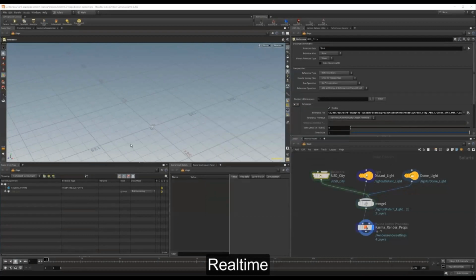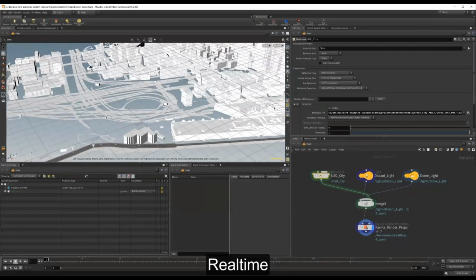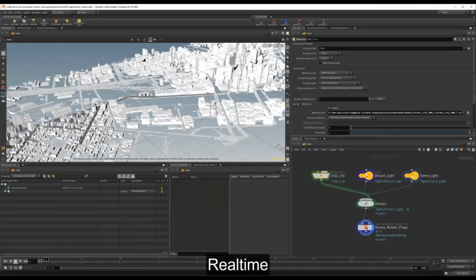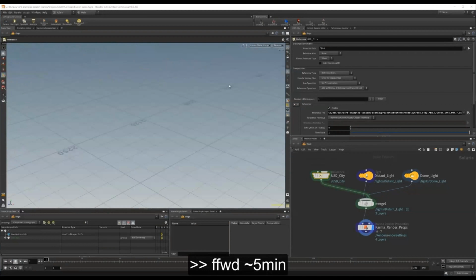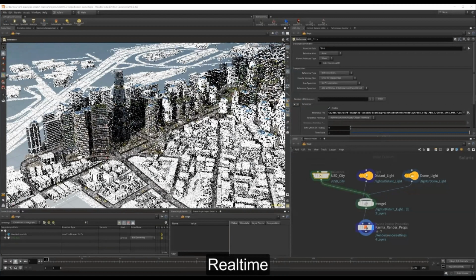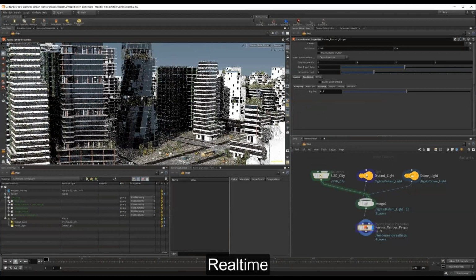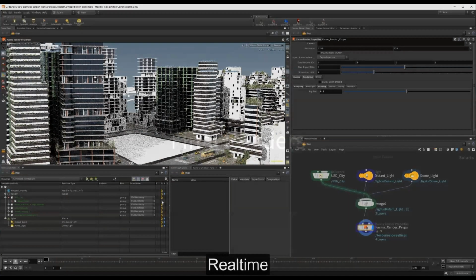This export contains about 50 million polygons, so a small to medium scene, and it loads fairly quickly in the OpenGL viewport of Houdini. So it's certainly much faster than older formats. If more advanced performance control is necessary, you can also export CityEngine twice in low or high-res mode and use LOPs or TOPs to switch between the two. Finally, we can switch over to Karma, as seen here, and explore the scene a bit more. Note how you can still quickly hide certain buildings also in Karma mode.